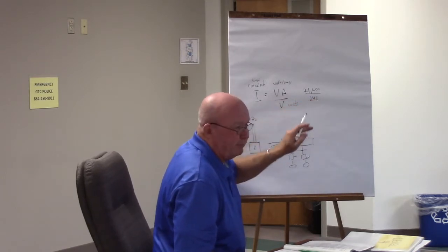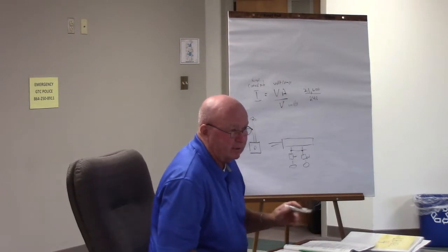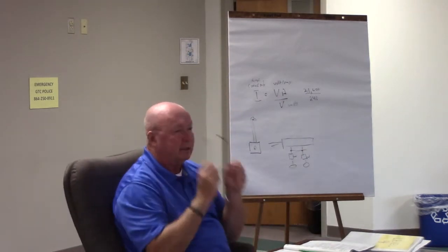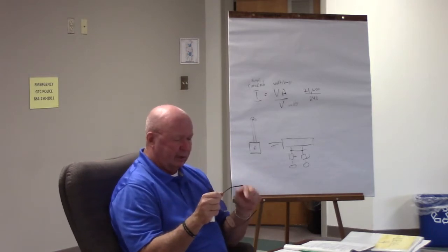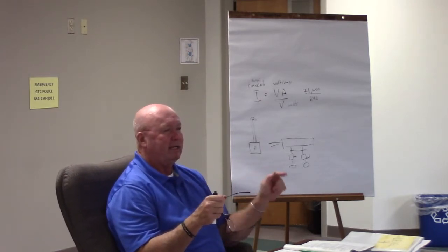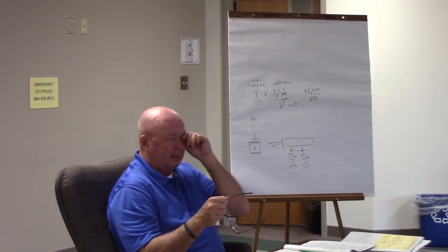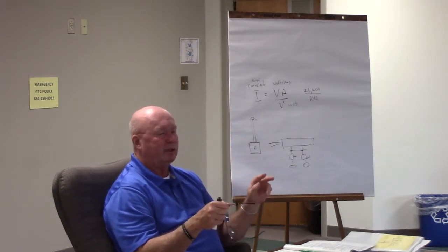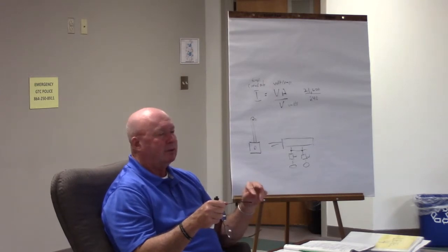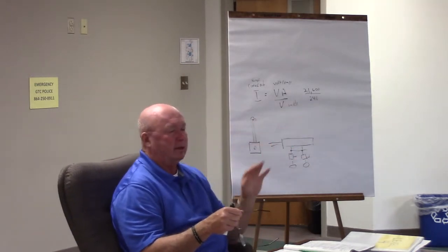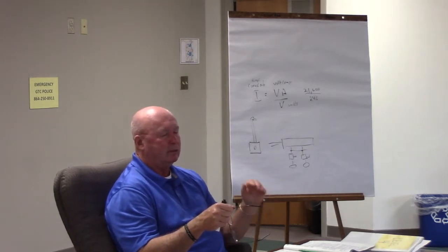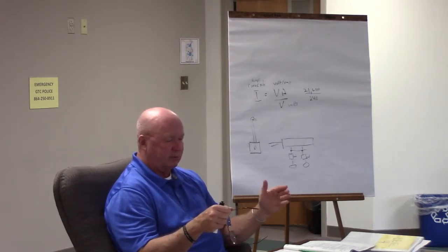Now that's actual voltage. That's very important, because that could have been a single phase 230 volt rated motor. But if you're single phase, your actual voltage coming in is 240. So you've got to use 240, not 230. Don't use the rated motor voltage. Use the actual voltage.